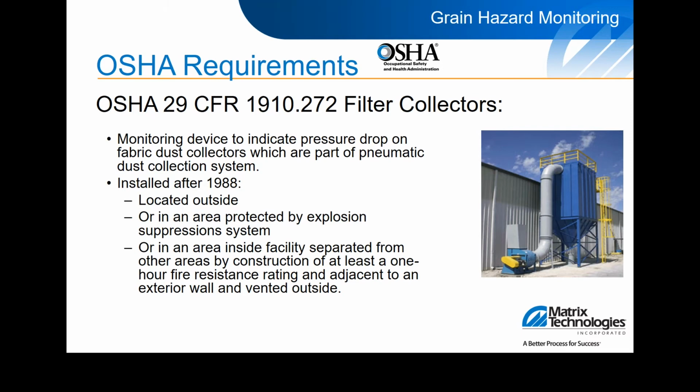Best practice design for dust collectors would be to locate units outside. I've recently seen a trend of these units being placed on rooftops of older facilities or in spaces at a premium. Attention to detail around how the dust filters will be maintained needs to be taken into consideration to allow access for platforms and rigging of hoists to help move larger equipment around to maintain the dust collectors.